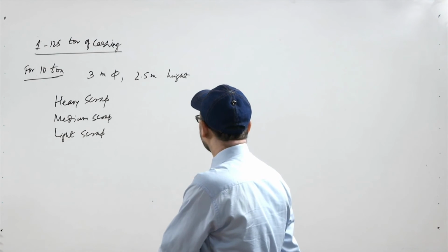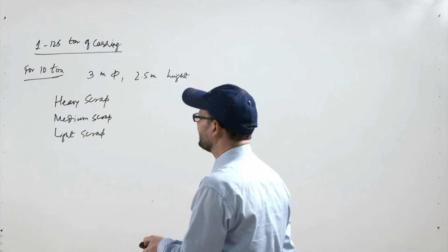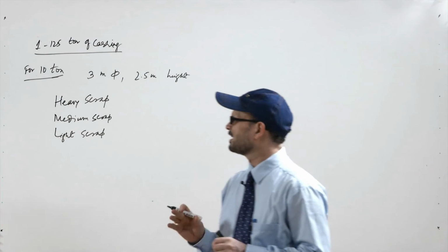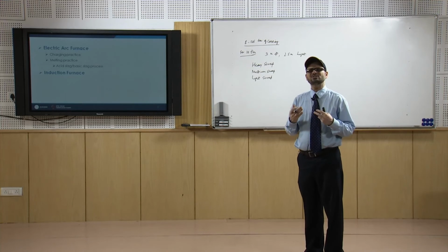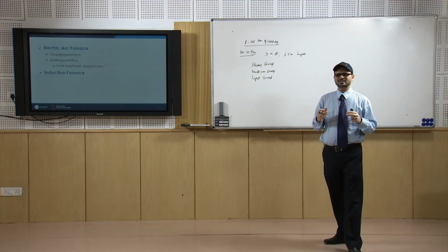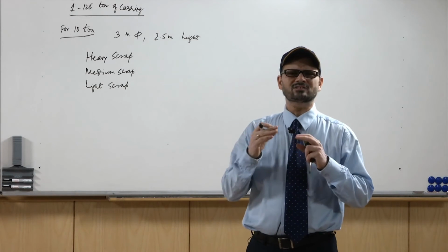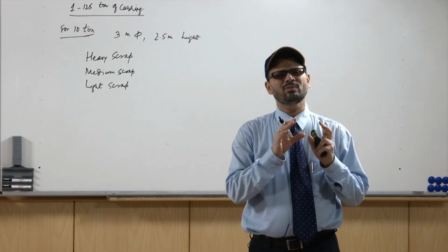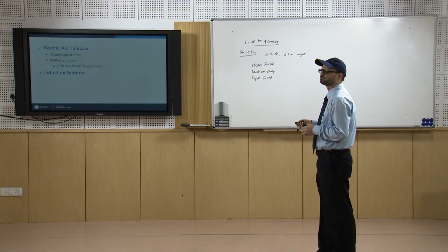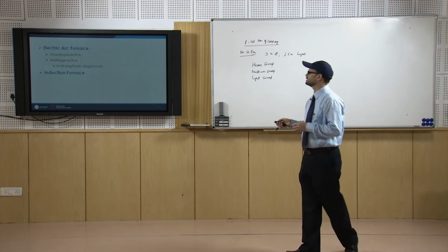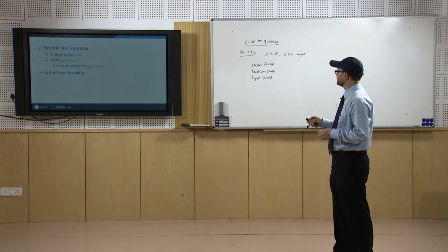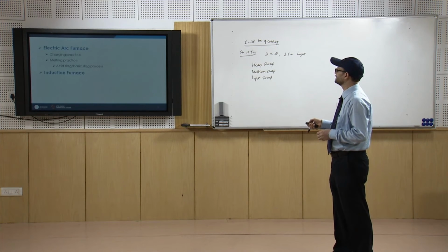Now, in this case what we do is, you have acid lining or basic lining. That is done depending upon the type of slags which are in practice. As we have discussed, in certain cases for composition control, like suppose if you want to control the amount of sulfur and phosphorus, you will have to go for the basic lining process. So, basic slag has to be there. Basically, these basic linings do not react with these basic slags.